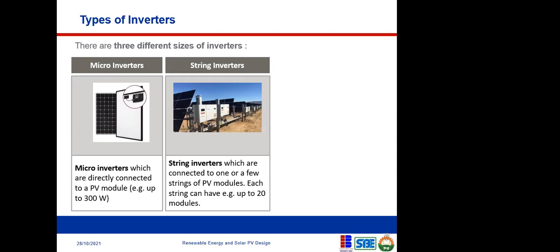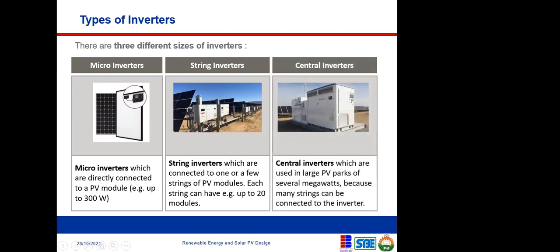Okay, so let's proceed. I think, for the person that asked the last question, a string is a collection of solar PV panels, maybe 3, 4, connected in either series or parallel on one side. Then you have another string. So it's still all going into the combiner box, but they are coming in strings of 12, or strings of 20, depending on the voltage that you want. Maybe after the next slide, we'll get there.